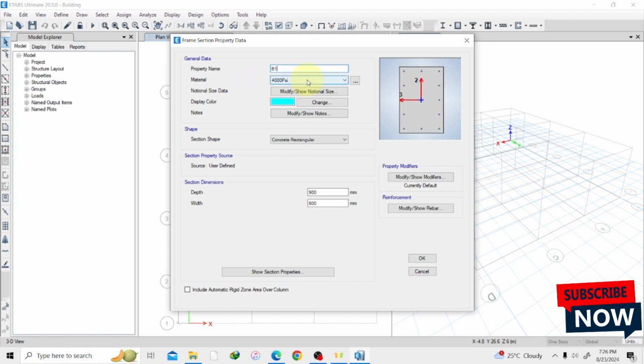So we have our material here. In our beam we have our concrete and we also have our rebar inside. But the material we'll be using here, in our previous videos, we already created a concrete we'll be using throughout our design. That was C30. So that's the material we are going to use in our beam. So we just go through and we have, okay, C30. If you remember, this is the material we created. So C30 has a compressive strength of 30 Newton per millimeter square.